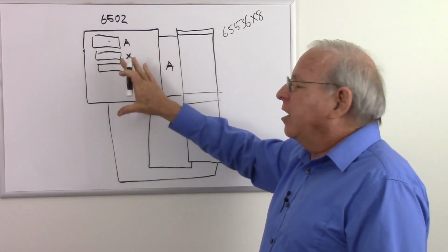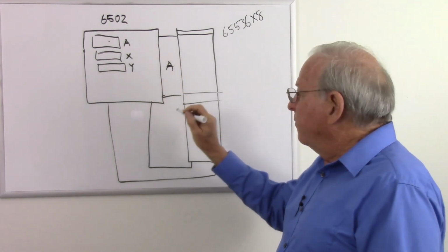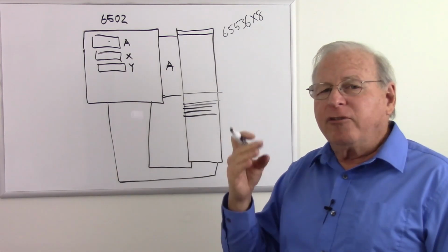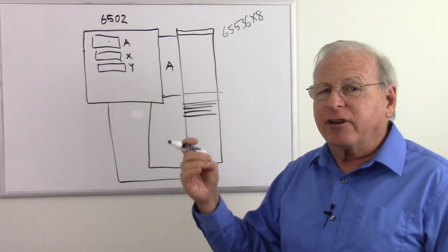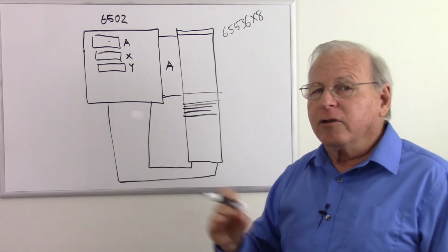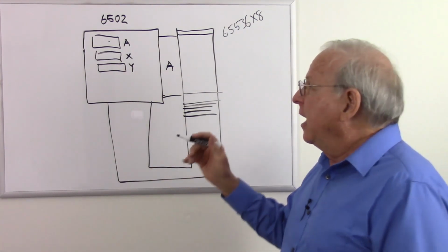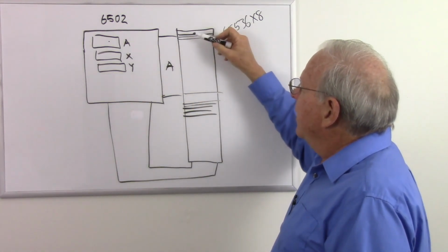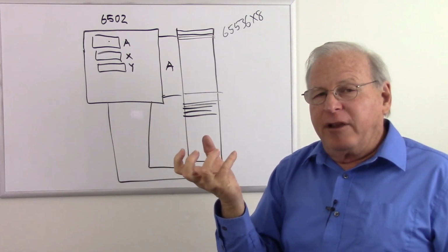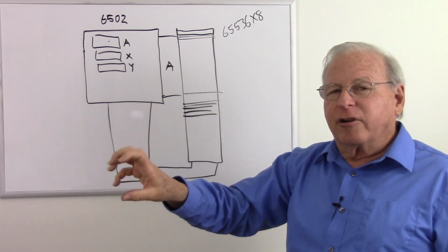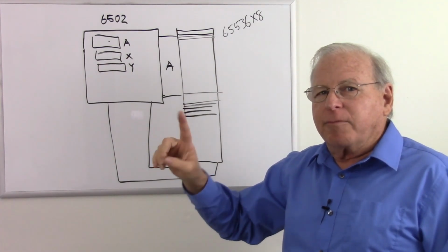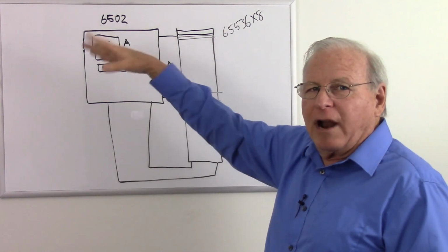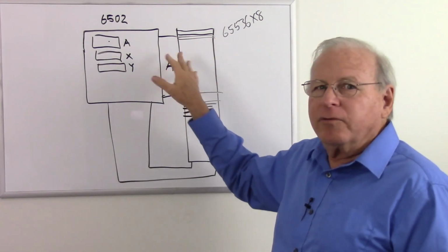And now we've said that we can add, subtract, multiply, and divide, and if we do a number of instructions, we can actually do a square root. And once you can do addition, subtraction, multiplication, division, and square roots, you can do any mathematical operation you need. And so this microprocessor, by following those instructions, this instruction, that instruction, is pulling in 8 bits of information, sticks it into an instruction register, decodes that through some circuitry, which makes a sequence of events happen, which either pulls something in, puts it out, or adds, or subtracts, or moves some bits, or whatever.